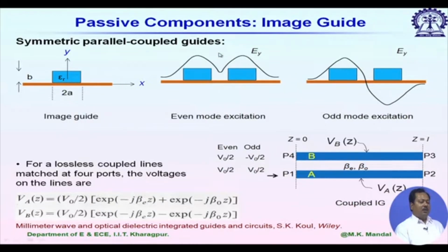If you remember, for the microstrip line case, we can use one PMC between these two coupled lines. Here also it is almost similar, and for the EY variation in odd mode, they have positive and negative values for the left and right hand side.